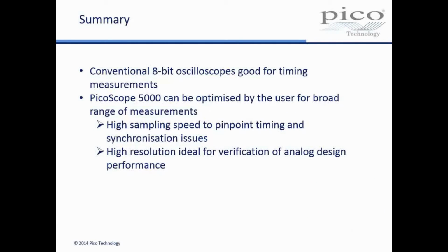If only 2 channels are required, then resolution can be increased to 15 bits, and in single channel mode all the analog to digital converters are combined to give a 16-bit mode at 62.5 megasamples per second.